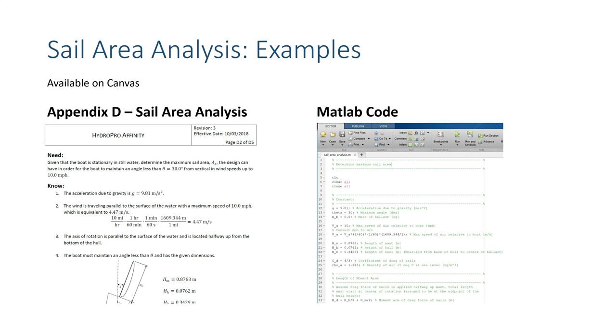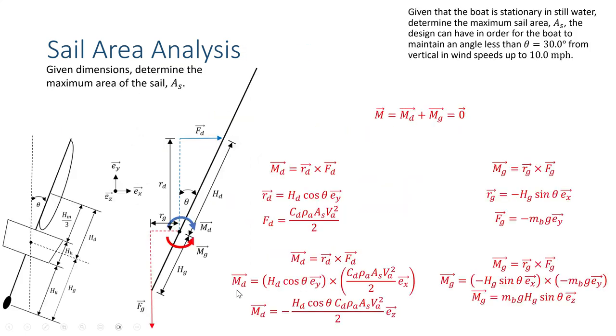Whereas a single hull design, you don't have that, and so you have to put a ballast at the bottom. And so think about the variables that you have to play around with to make your boat more successful. You could change how long your keel is. However, if you make it too long, it's going to drag on the bottom of the pool, which is not good. And the pool depth is about 13 inches. Now, you don't want to push that right at the limit because it might drag in certain areas of the pool because there's some wrinkles in the bottom of it.